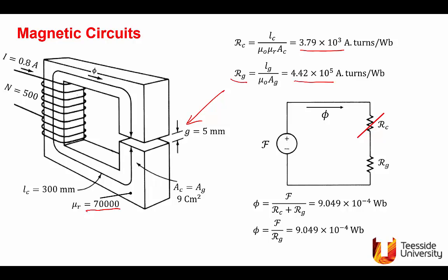We use the iron core here to carry the flux, but this flux is supplied to the air gap, which is the highest reluctance by far in the circuit. In other words, we can assume that the magnetomotive force Ni is acting on the air gap approximately. In this case, the integral of H dot dl will be H multiplied by G. This part here, the integral of H dot dl, will approximately equal H multiplied by G. Ignore the rest of the integration.